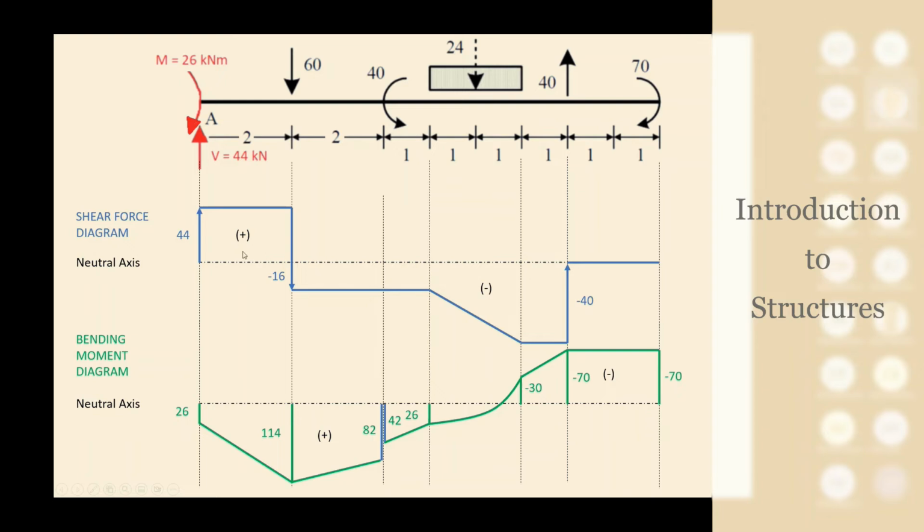It's very important for you to check this relationship because it is very useful to interpret and check diagrams and to find errors. In an exam, for example, if you find that you have a parabolic distribution and suddenly a constant shear force, something is not right, so you have to correct it, because this is the correct relationship between these two diagrams you have on the screen.